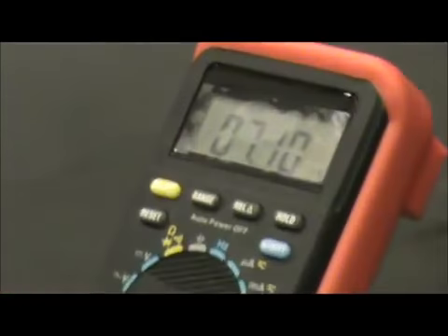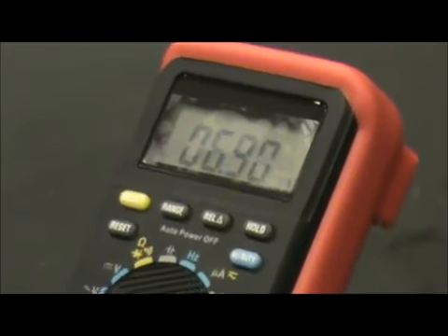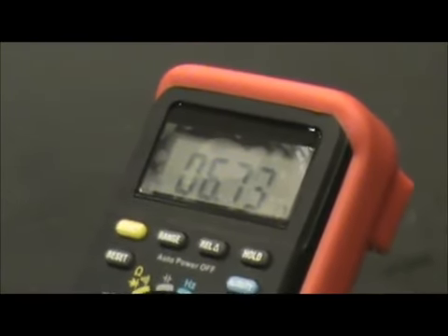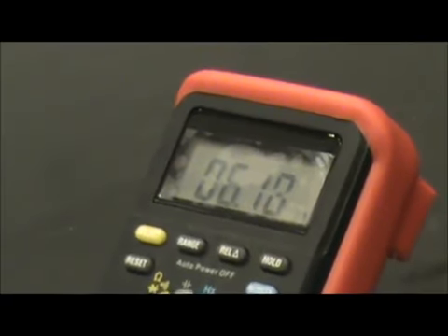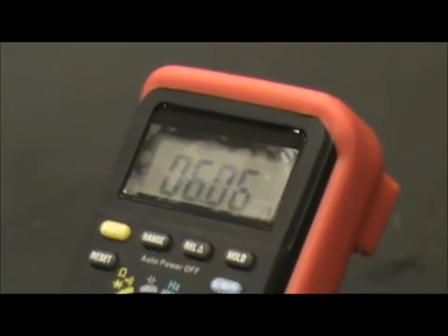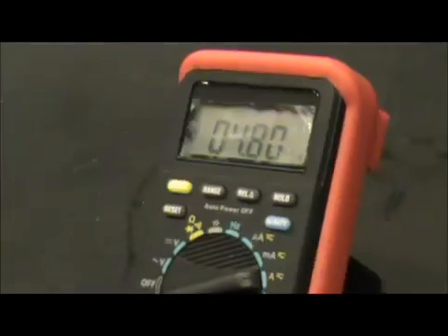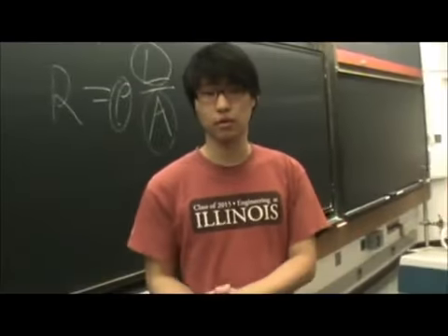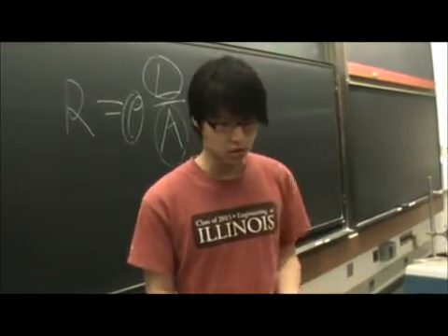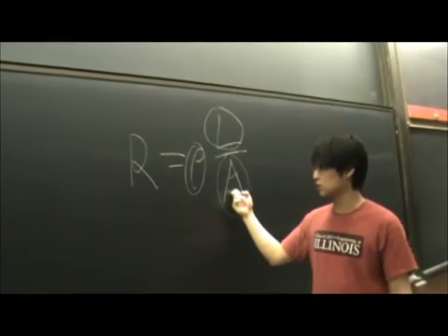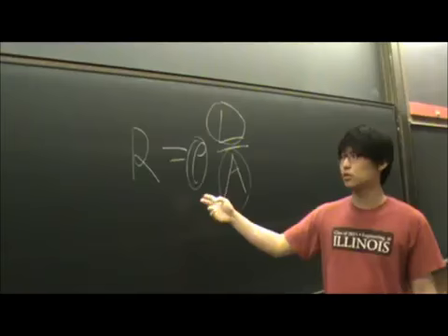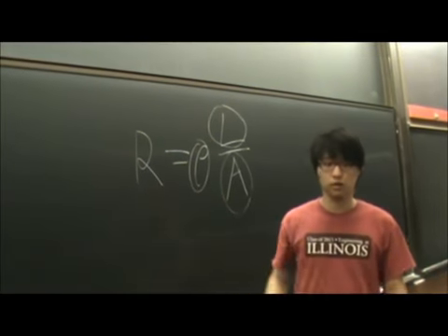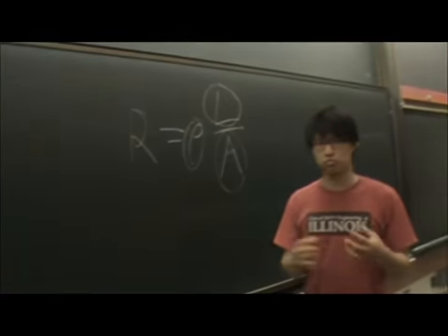Now let's look at the results. Check this out. Now we see a current of around 6 ampere. Now that tells us that having the same material and the length, the cross-sectional area is inversely related to the resistance. Throughout this experiment it was shown.